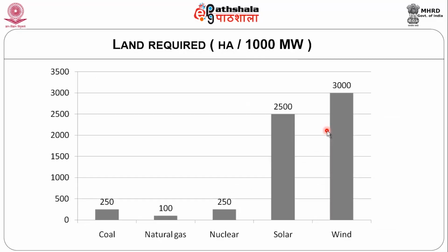And so in this lecture, we have seen so far about the land requirement and the Betz limit. Importantly, we have seen how much energy could be tapped, and the derivation from Bernoulli's equation: what is happening upstream, what is happening downstream, and what is happening at the rotor. We equate these and arrive at the Betz limit, which is about 59.3%.